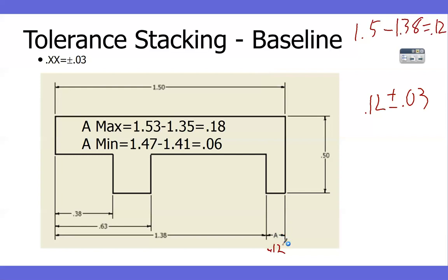So this is why we don't put all the dimensions, because that would be different than what we did with the math. So that's called tolerance stacking, okay? So in baseline, all we have to worry about is those 2 dimensions here. What if I cared about this part right here? What dimension is what I care about? Yes, now I care about these 2 dimensions, right? But still, it's only those 2.